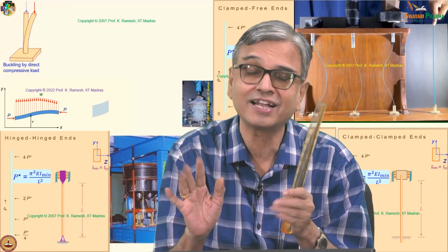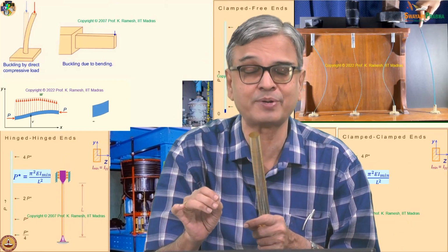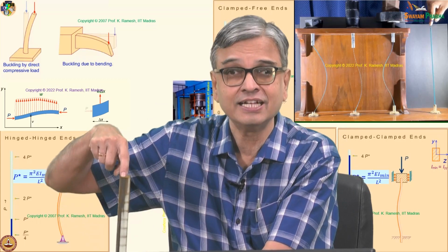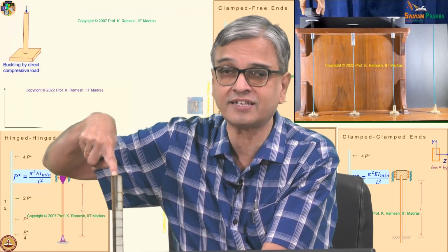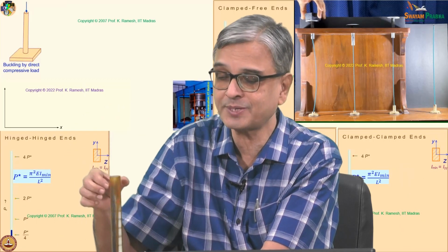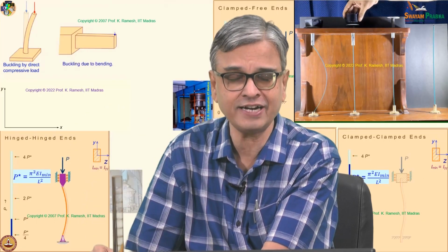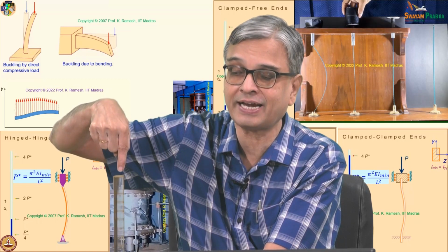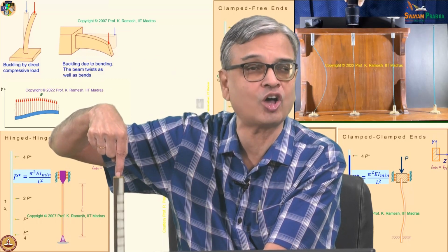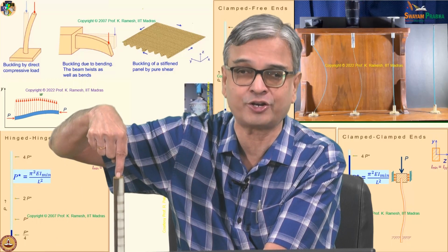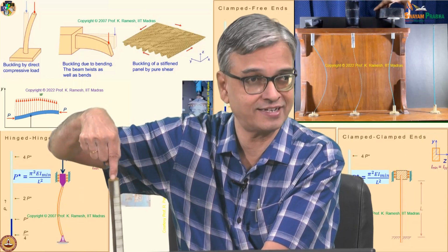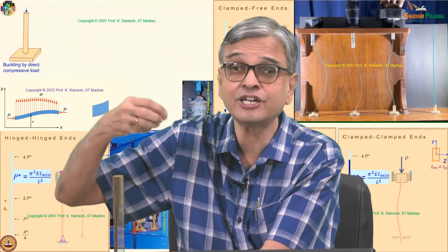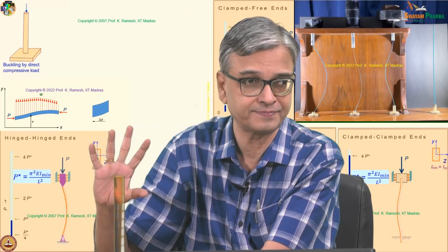No, it is dictated by the moment of inertia. Because I have taken a circular cross section, the probability exists in all the 360 degrees. It could be precipitated by inherent defects. It could also be precipitated when I apply the load. I may not apply it exactly along the axis as intended. There could be an eccentricity. So, there is a perturbation introduced in the process itself.